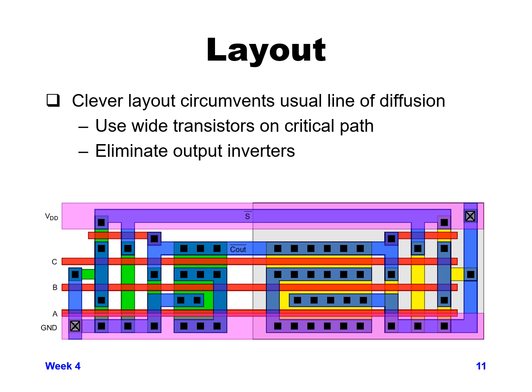Like I said, if you had rotated the layout that we normally do, where PMOS is on top and NMOS is on bottom, here PMOS is to the right. The really wide devices that you see there are the carry in to carry out path, whereas the narrower devices are going to the sum out, and we care most about having a fast path from carry in to carry out.